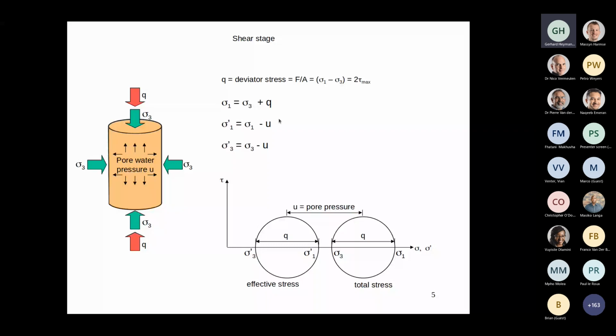Okay, so here you can see all the equations that, again, you need to plot your Mohr circles and also stress paths, and I'll explain stress paths in a minute. There are a few details with things like area correction and so on, but that's pretty straightforward. So again, I'm appealing to people who don't regularly plot their own stress path. Do it. It'll give you much more insight into the behavior of your material. It is not wasting time. It is a valuable exercise. Okay.